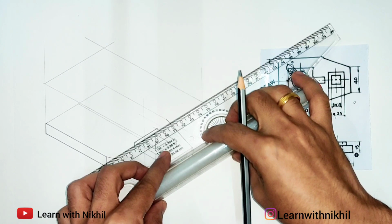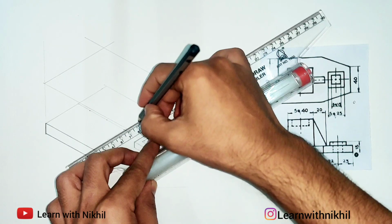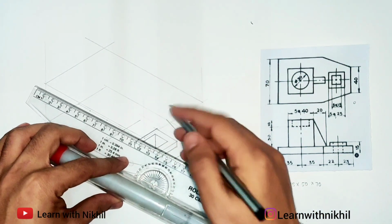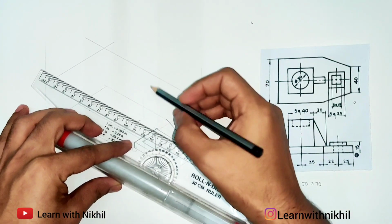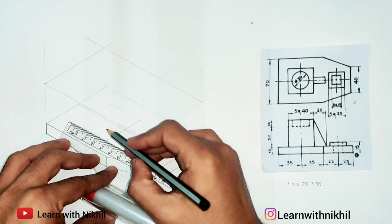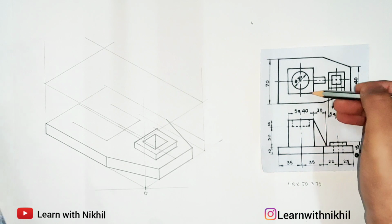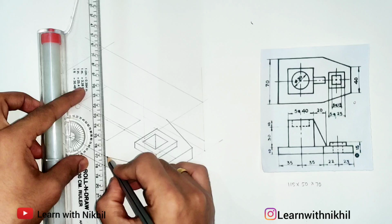So likewise we have to create a square again. From here draw a line, light line, and from the center it will be a side of 40. So this is 40. From here again light line, from here light line. So this distance is 40. You can complete the total square, but as you know, the square has a height again of 40 millimeter, so it will be hidden behind. So I am not drawing it completely.